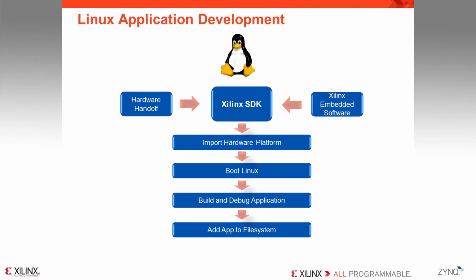Linux application development for the Zynq platform is similar to other Linux development processes that are hardware and platform independent. The procedure for creating applications in the SDK workspace is similar to the standalone platform, except the Linux platform BSP is selected. Linux development and debugging can be executed in the SDK or in an external Linux development environment. The PetaLinux tools offer everything necessary to customize, build, and deploy embedded Linux solutions on Xilinx processing systems. Once a file system has been created with these tools, the SDK provides easy integration for application development and debug.